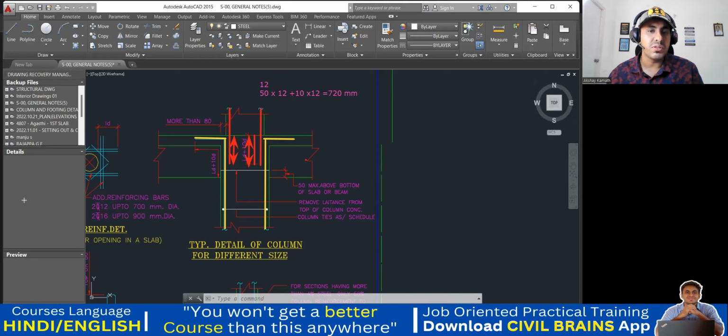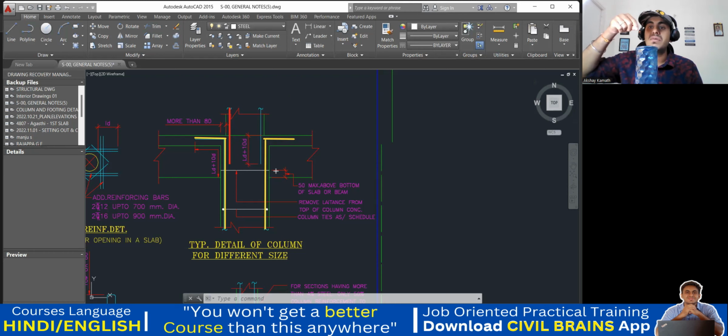So usually what we do is we'll try to drill a hole. For example, I have a bottle. If this is my column which is ending, I'll drill around, this much amount it has to go. How much? 720 mm it has to go. So you'll insert 720 mm inside this particular thing, and from here you will take your bar. You getting my point? Here, of course, drilling is not required, because anyhow we will insert a new bar.